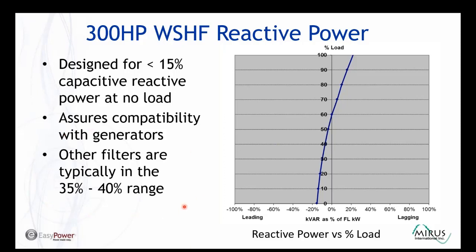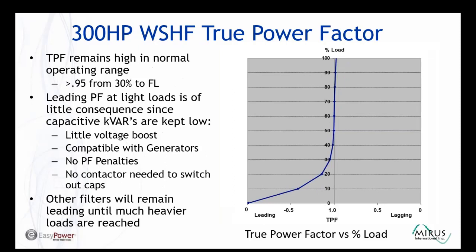Again, many filters will fall into this range here with the capacitive reactance, which, as mentioned earlier, can create issues with generator applications. And if you keep your reactive power low, then you're going to have a much better regulation of power factor on the input of the drive.